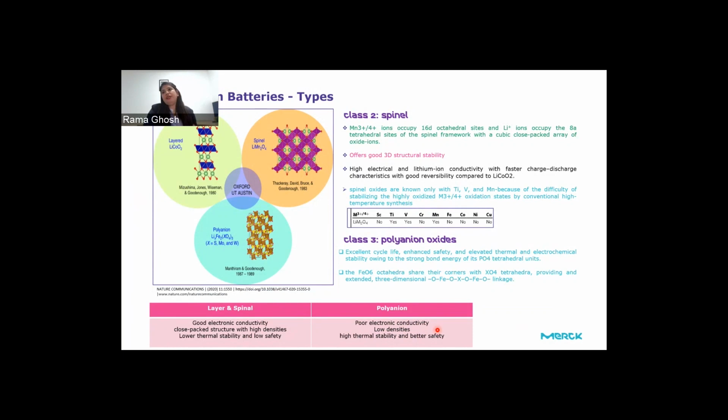They are using coating chemistry, coating lithium iron phosphate with carbon, and also doping with metal elements or non-metal elements, so that they can increase the potential of the features, which also enhances the safety and at the same time reduces the cost of the final battery.